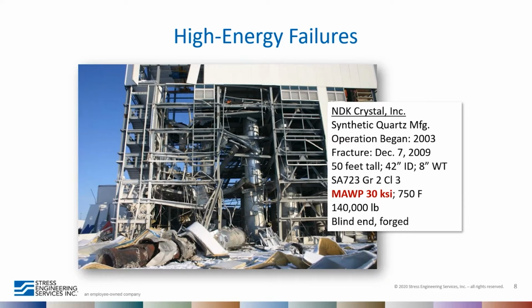Now, the sodium hydroxide represents a corrosive substance against the carbon steel, but there is a passivation layer that's built from the initial reaction of the hydroxide against the steel. And the owners of this vessel expected that passivation layer would protect them from further corrosion. Unfortunately, they did not have a good inspection program, and it turned out that that was not quite adequate. So as a result, they had a failure, a major failure.